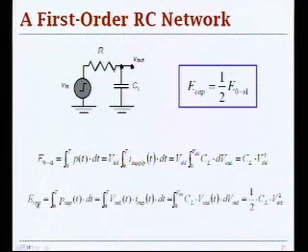So now let's see how much energy is stored on this capacitance, on this gate capacitance at the output, because that is actually the useful energy that is related to the information in digital format, 1 or 0, at the output of your gate. You would want to spend a certain amount of energy to be able to say, okay, I have a high voltage here, that's my logic 1. For that purpose, to calculate the energy, you integrate the power of that capacitor over time.